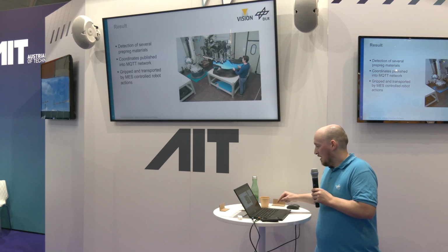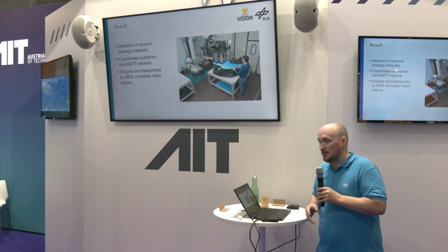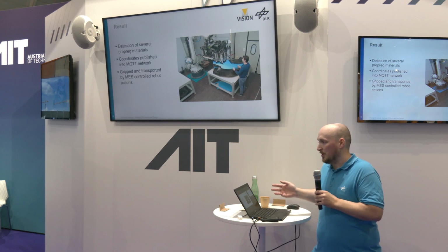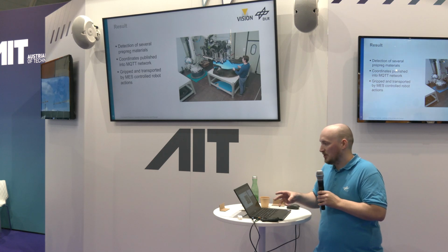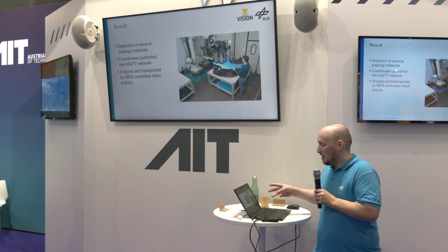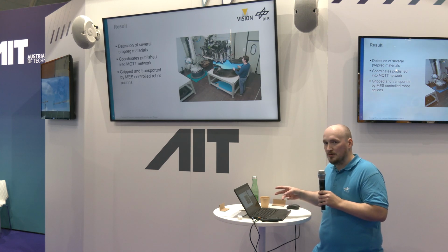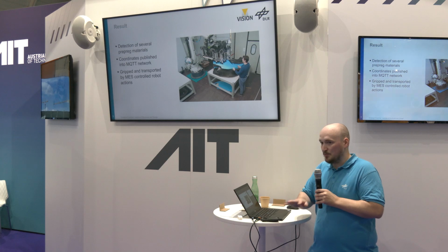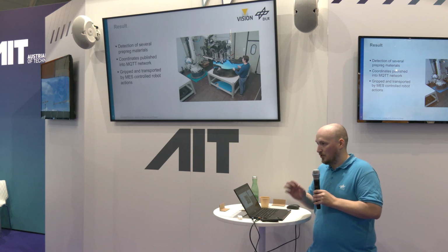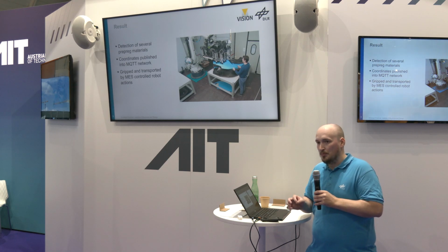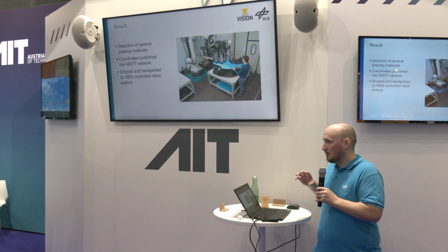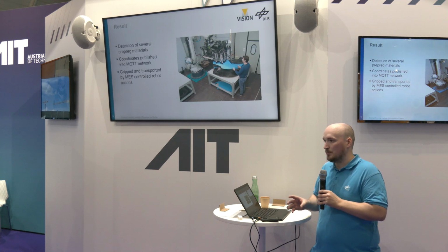And how this is looking then during the process, here you can see how one worker is transporting the fabric from the table where it was gripped to the mold. And here it's especially important to grip it correctly, since the pre-preg is already sticky, and as soon as you touch the surface the first time, it's placed. You can't change it really. So the first lamination point needs to be really precise, and that's what we could establish really nicely with the system, because we continually grab the cut piece on the correct position.